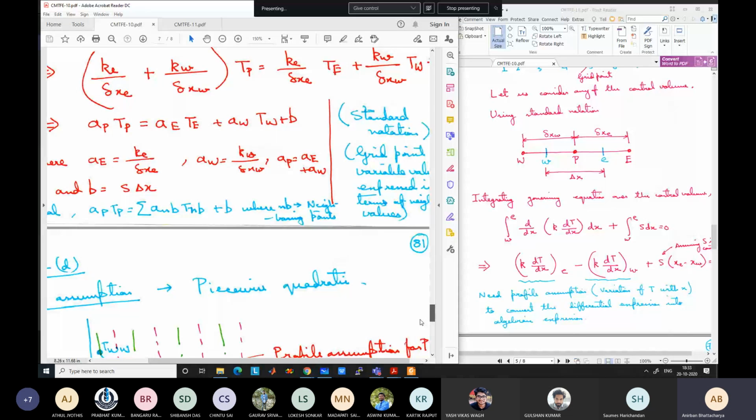And for each of the control volumes, what are the coordinates of the vertices? So for example, if this is the 11th control volume, what are the coordinates of its vertices? Okay, it is storing that, and based on that it can easily find the centroid. Okay, and any other properties like what is the slope of each of these faces, what is normal to each of these faces. All this can be calculated if you know the coordinates of the vertices. So that is what meshing software does.